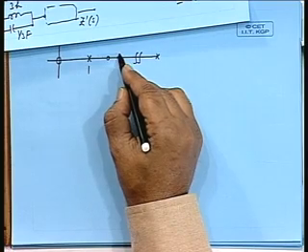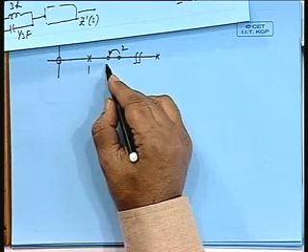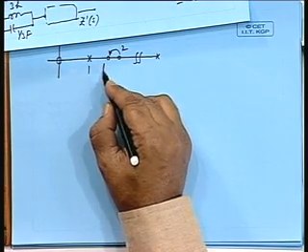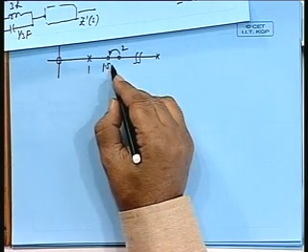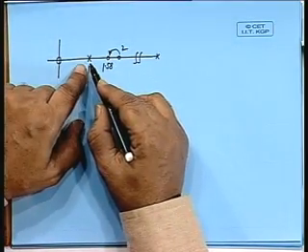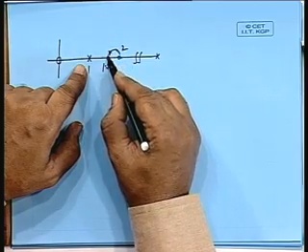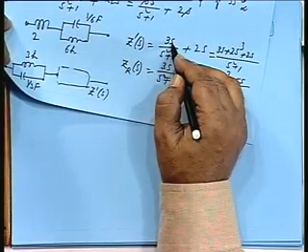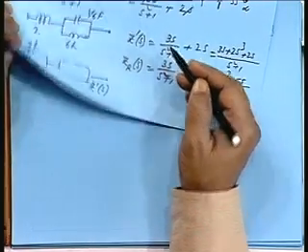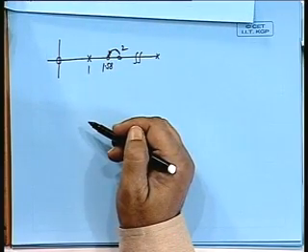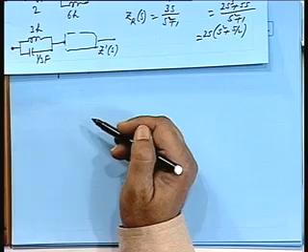Okay. So, this 0 at 2 has now shifted to root over of 5 by 2, approximately 1.58. So, if I weaken a pole, I can shift a 0 to a desired position. I have taken out only 50% of this 6s, this residue. I could have taken any percentage, and hence I could have shifted this to a desired location. Therefore, by partial removal of a pole, I can create a 0 at a desired position.